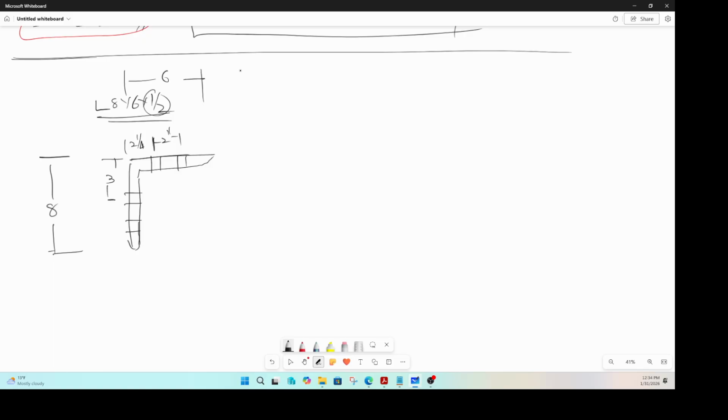The question is pretty easy. How do you determine the LRFD design strength? Yes, it is a tension member. The question is pretty straightforward. It is nothing but area times the stress, but then which area, what stress? That is what makes the whole thing a little more complicated.